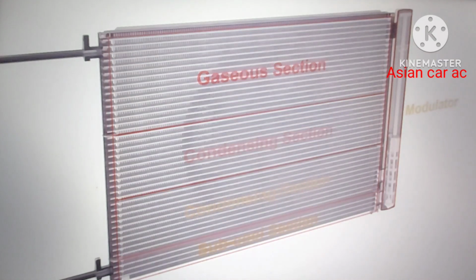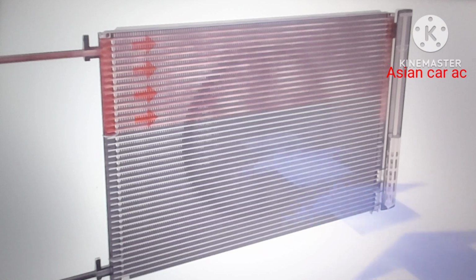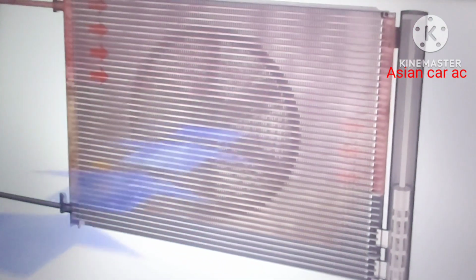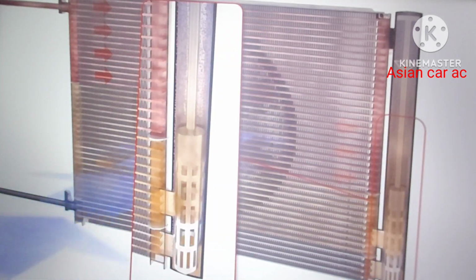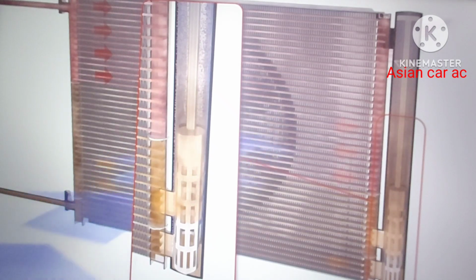The gaseous condensing and subcooling sections consist of tubes and fins, and as the refrigerant passes through the gaseous section, the heat contained in the high-temperature refrigerant gas transfers through the fins to the outside air. This loss of heat reduces the gas temperature, which allows the gas to condense within the condensing section, where it naturally changes state to a liquid.